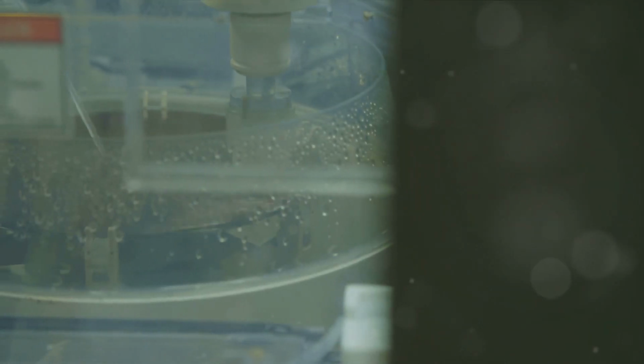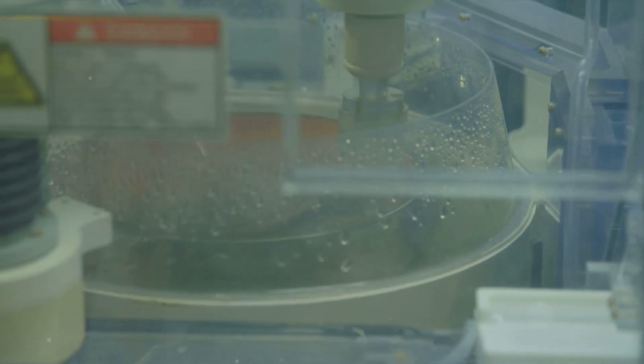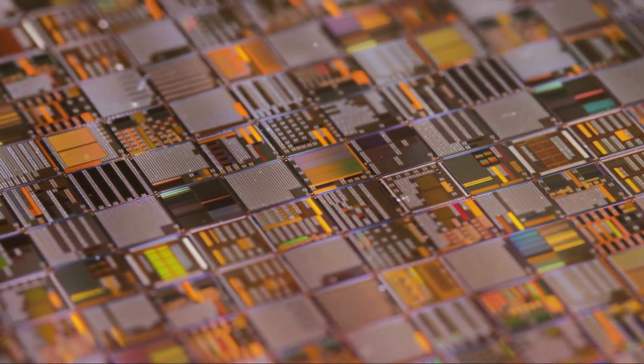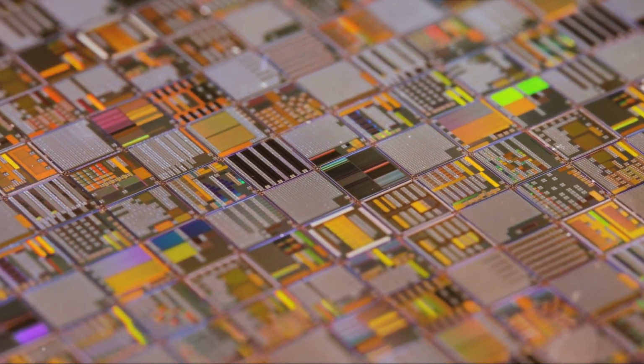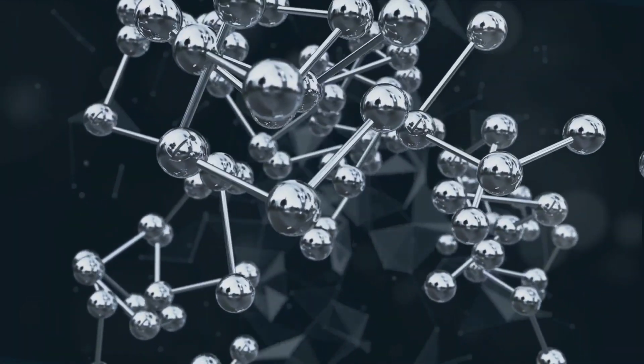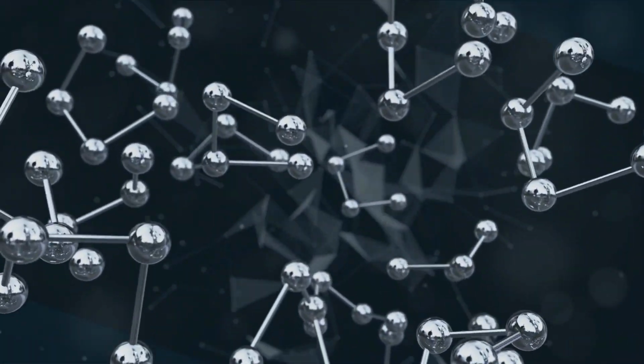Then, we dived into the heart of our topic, the PN junction. This is where a P-type semiconductor, laden with positive charge carriers, meets an N-type semiconductor, teeming with negative charge carriers. The meeting point forms a junction, hence the term PN junction. We delved into the inner workings of this junction, discussing how the movement of electrons and holes across this junction results in the formation of a depletion region. This region acts as a one-way street, allowing current to flow in one direction only. This is the principle of diode, a vital component in electronics.